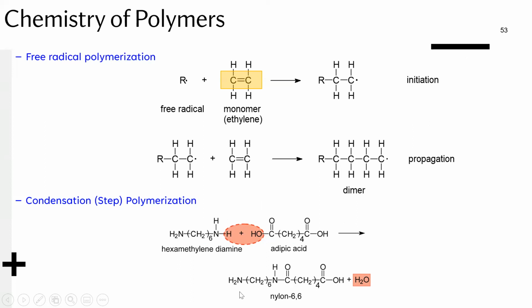So, for instance, nylon is a condensation polymerization process where there isn't a double bond to be broken. Instead, you actually swap these two. You have a water molecule going through condensation, and then these two monomers connect to each other. And so nylon indeed is, I would say, a two monomer content sort of material.